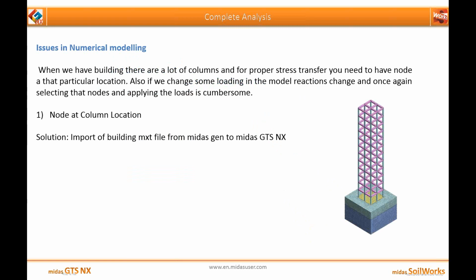Now when we have a building, there are a lot of columns, and for proper stress transfer you need to have a node at that particular location. Also, if you change some loading in the model, the reaction will change, and once again selecting that load and applying it on that particular node is a tedious process. Now just to summarize, first is the node at column location.